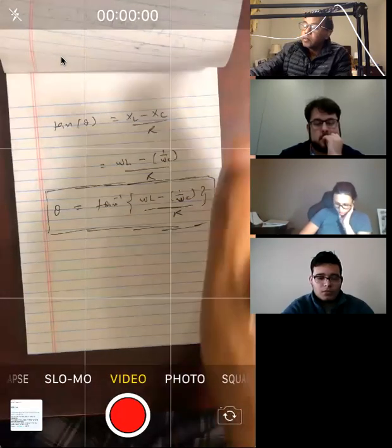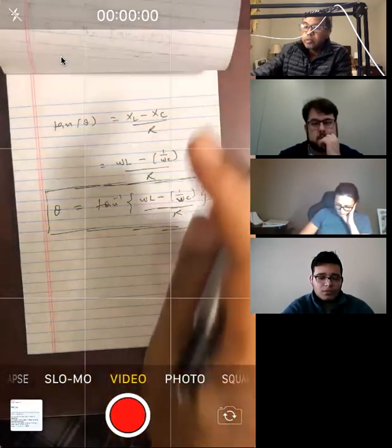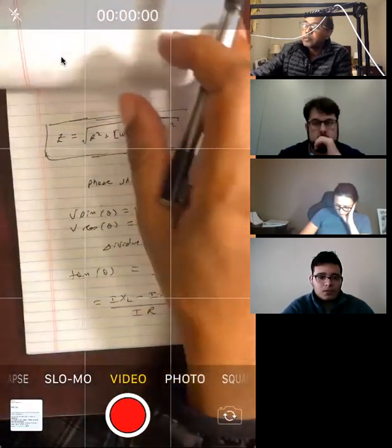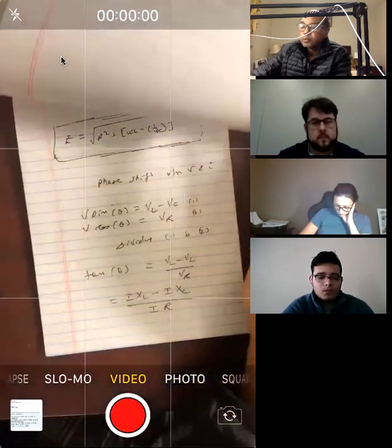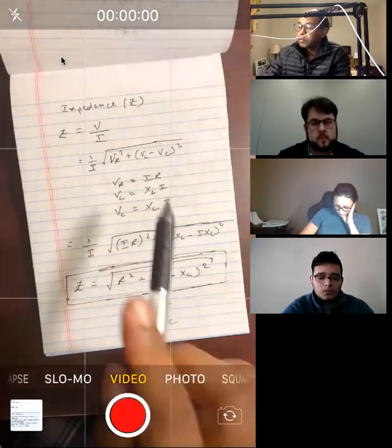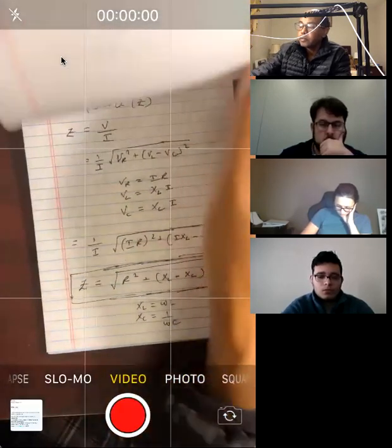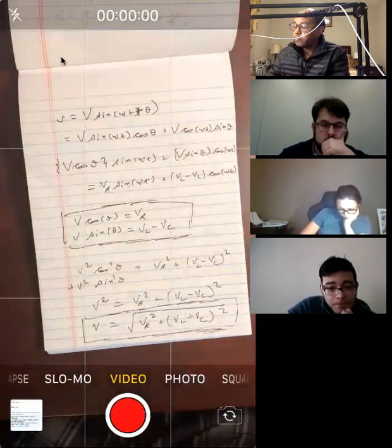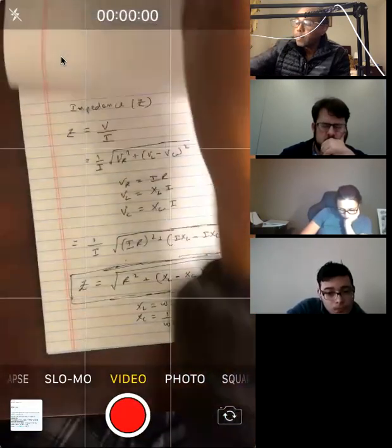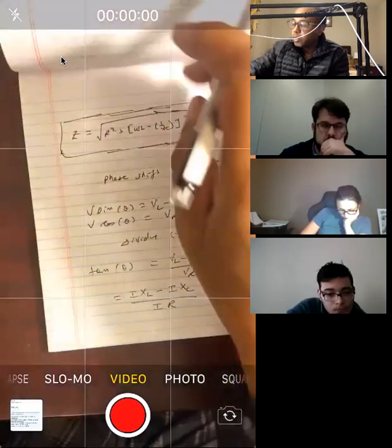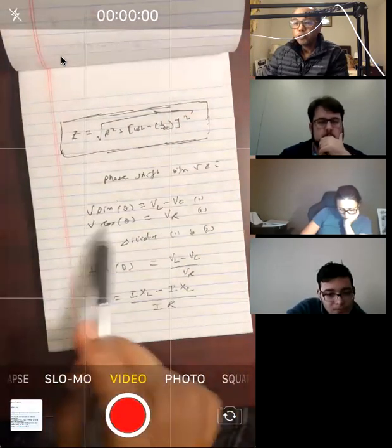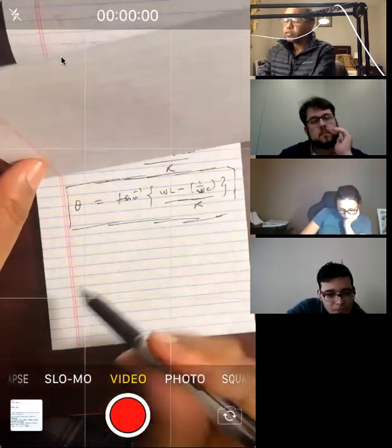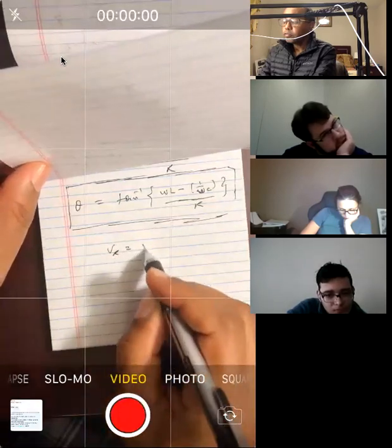So the important conclusion is the phase shift is going as follows, and the voltages are added like vectors, according to the equation over here: VR squared plus (VL minus VC) squared. Another useful formula for the phase shift: you see, we have V cos theta equals VR. We have VR equals V cosine of theta.